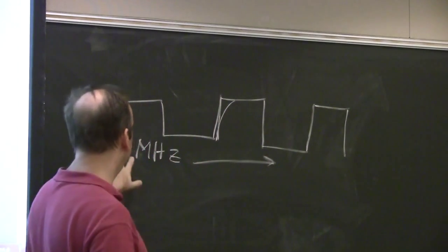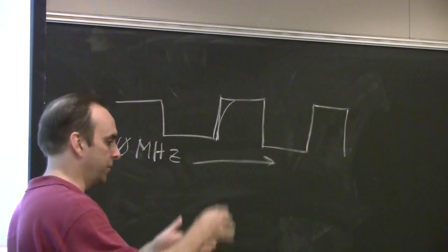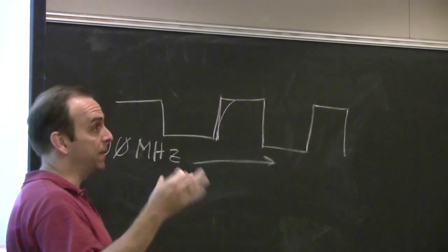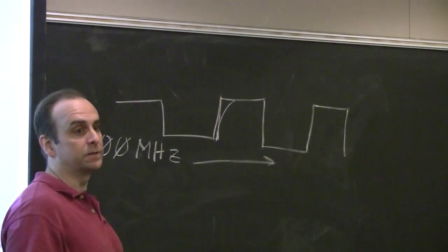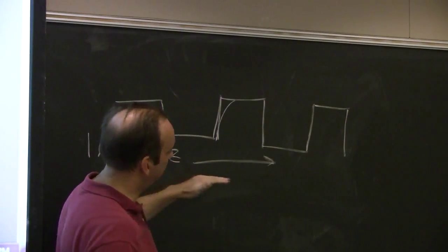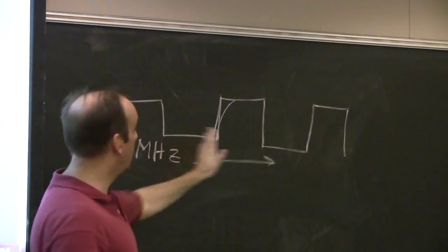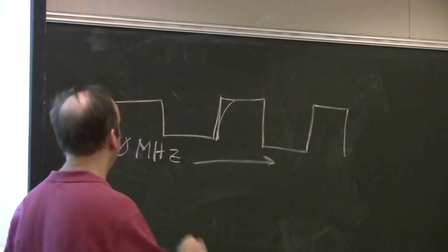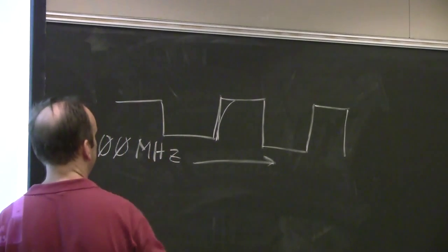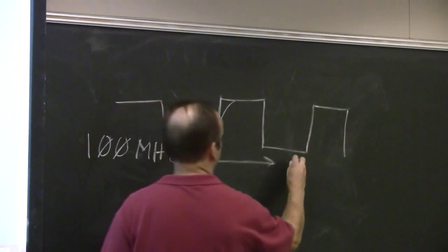Eventually the harmonics just diminish, because you can't have harmonics going on forever, because nobody can make a 500 gigahertz signal or whatever. So the amplitude of the harmonics begins to diminish. There's like a low pass function going on. But there's still some wide bandwidth that you care about. This signal has significant energy from about 100 meg, probably up to a few gig, like 2 or 3 gig.